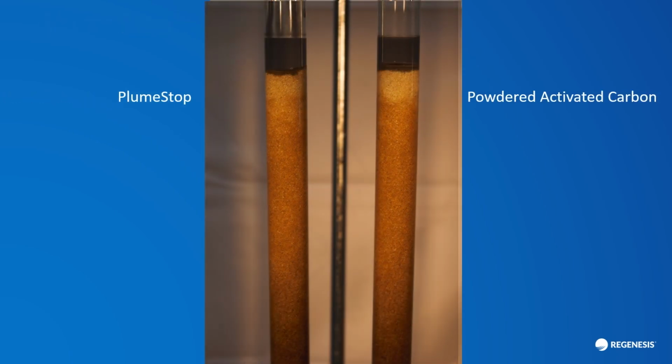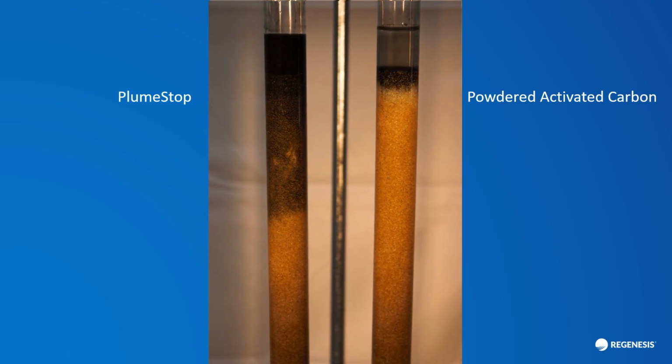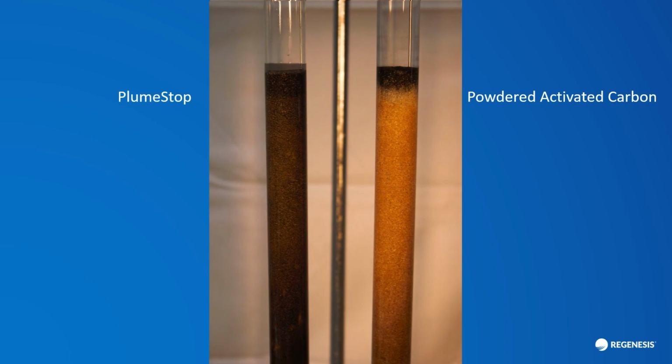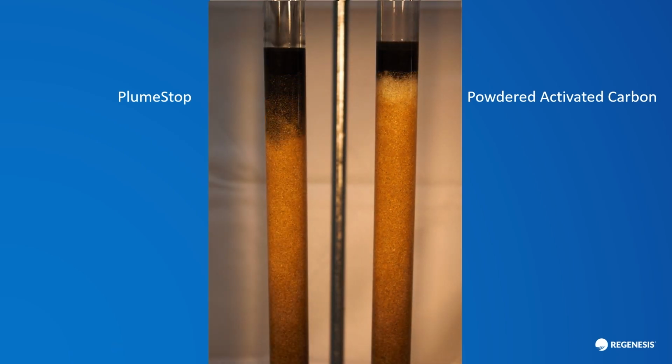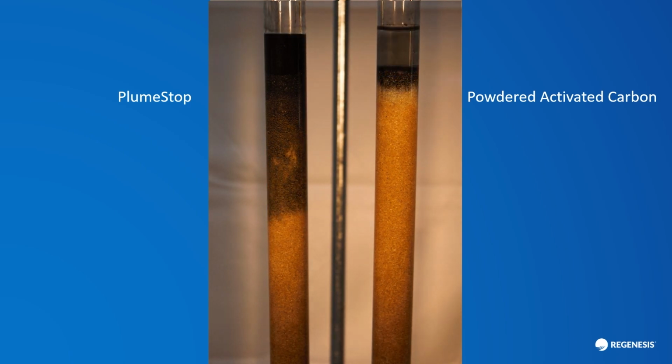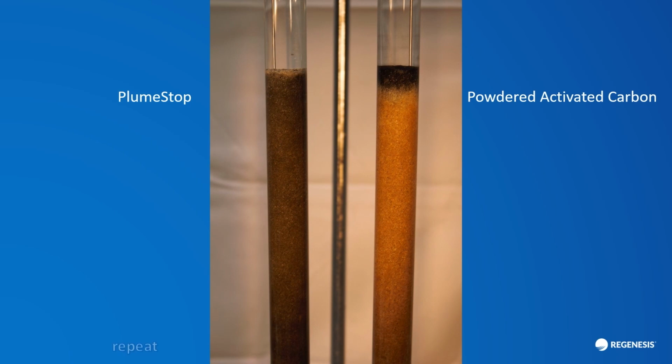And what we can see is PlumeStop being added to the column on the left, and powdered activated carbon, similar quantity, being added to the column on the right. We've looked at a time lapse over about 3 minutes, and we can see that the PlumeStop has just flooded down through the column, leaving a trail of black carbon on the soil behind it, whereas the activated carbon has plugged up at the top.